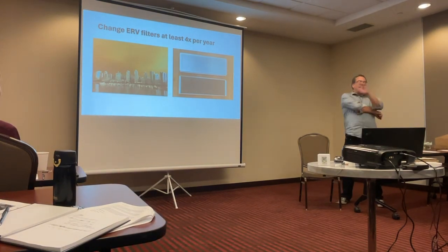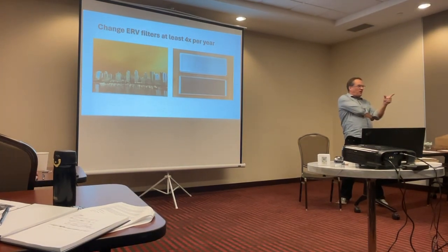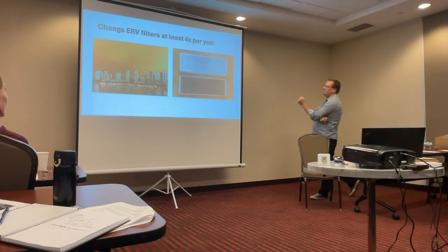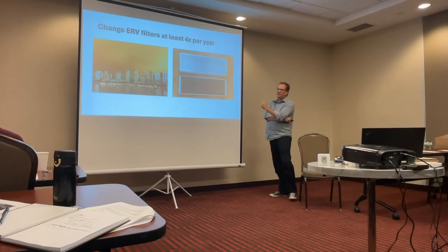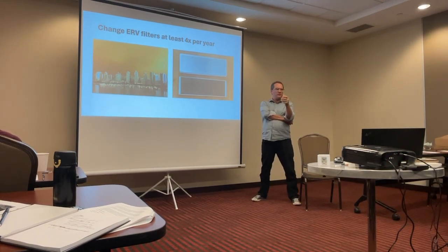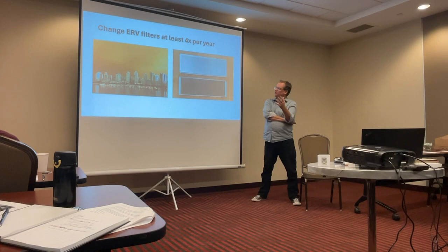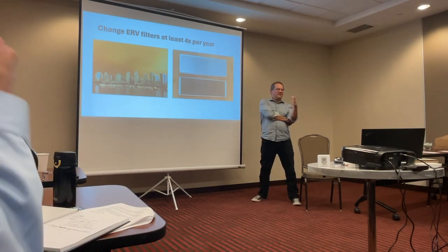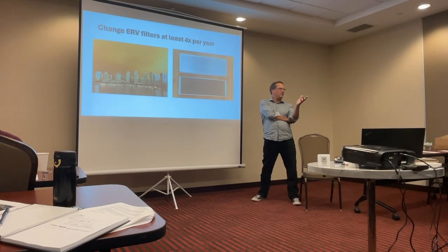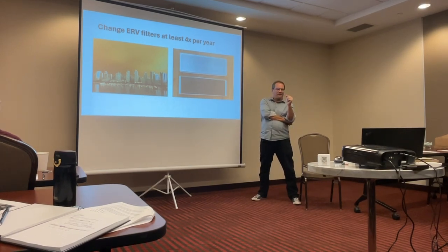Okay. Yes, there is no hard and fast rule about filter changes. But what I want to talk about is that we're seeing in urban areas twice a year is not enough. They're coming out too dirty, too clogged up. If you pull them out, you can feel the fan almost exploding. The fan's been bound for months and months. So we're starting at four times a year, but the real advice is keep changing them and see. If you're in a great clean location, you can get it down to once or twice a year, as you probably can in single family homes. Awesome. No, you can't, four times a year in California.